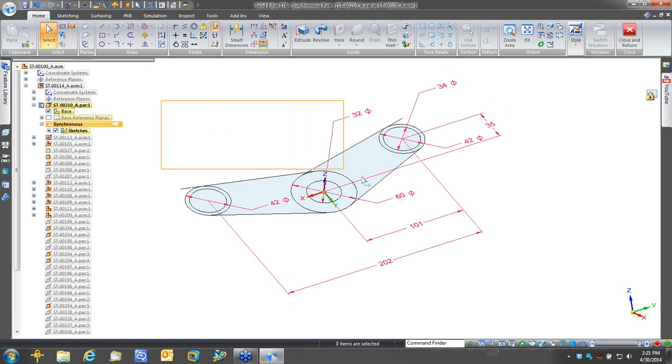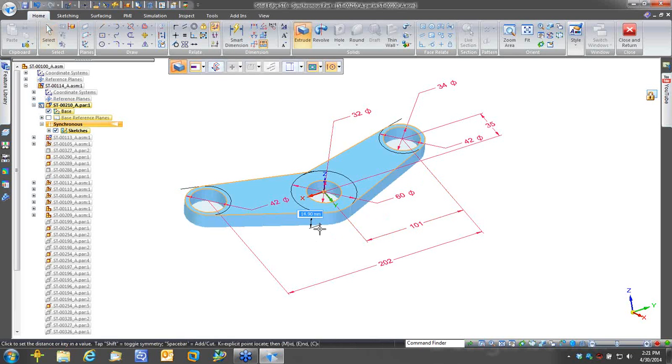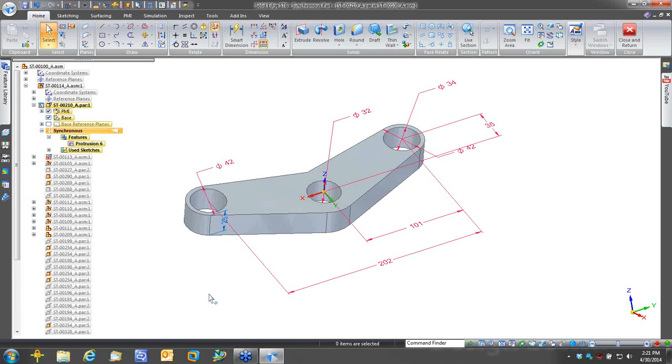Well, in Solid Edge, I don't have to do that. The system will do that work for me. So I can highlight everything automatically within a window, and Solid Edge will recognize each of those closed regions. And I purposely had some of those lines extending beyond the closed shape because I want to show you how Solid Edge will do the automatic trimming of those elements for me.